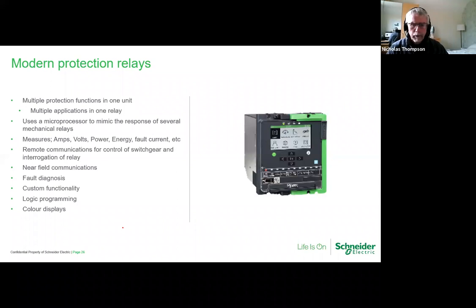And when we talk about fault diagnosis, we might need to know what's been going on before, during and after the fault, and that's called a disturbance recorder, which is becoming more and more standard within relays, and it will create what's called a COMTRADE file, and you can download that file, and it gives you all the waveforms, and you can see what's been going on with each phase and such like at your leisure if you're trying to work out what's going on.